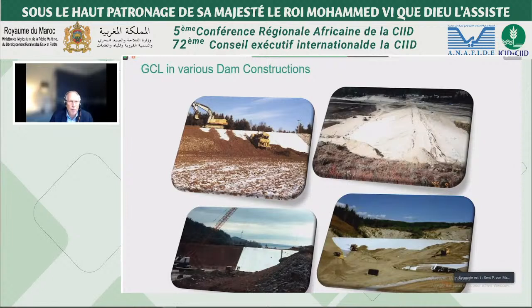There are various applications where these materials have been used. I won't go too much into details in those because you've seen some in the applications before. They typically all look the same because the applications are the same. The only difference between maybe a geomembrane and a geosynthetic clay liner is that a geomembrane sometimes does not need immediate cover or cover at all. They can be used uncovered, whereas a geosynthetic clay liner also would require around about 30 centimeters plus unconfining stress on top of it, but that's something which the design has to look into.